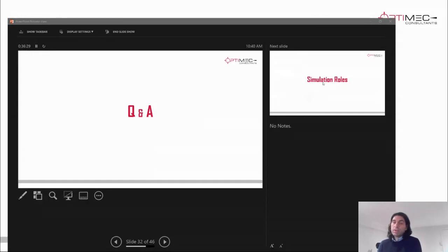So when you run it in interactive mode, you have to keep that window open for the simulation to run. If you don't want that, you should run it in non-interactive mode, so you can close the window and keep doing work on the platform. Does that answer the question?